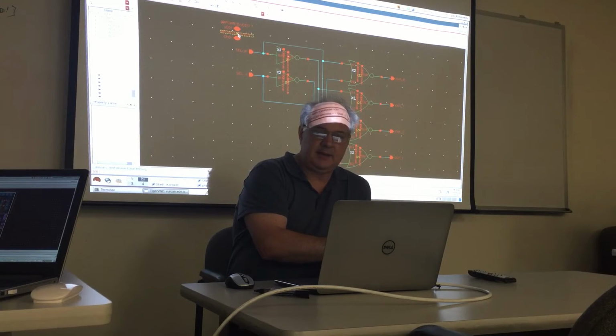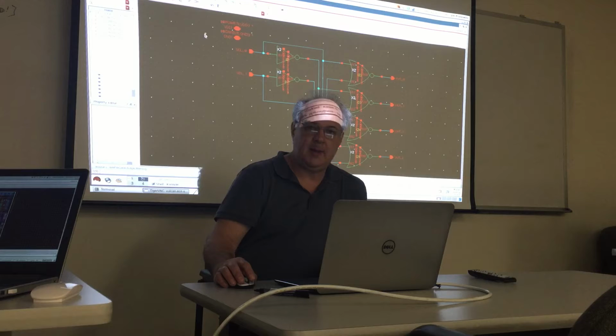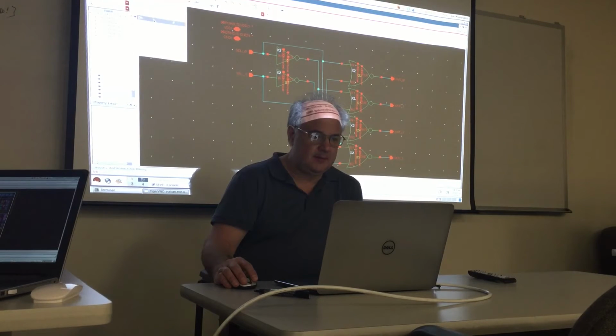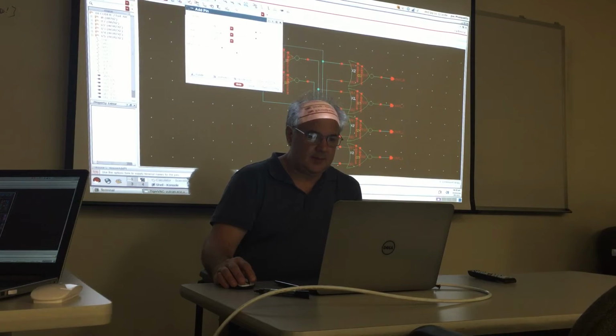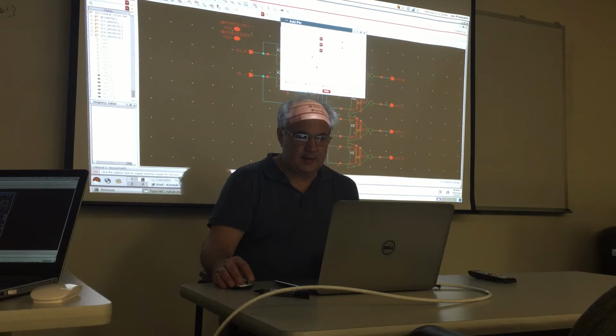So your PDK has examples of everything you might want to do. Schematic is actually fairly easy. When I create a pin here, you just create pin, right? And remember the VDD and grounds are special, so you type VDD, or in this case GND bang here, and then click the attached net expression, then GND there, and then GND bang here.